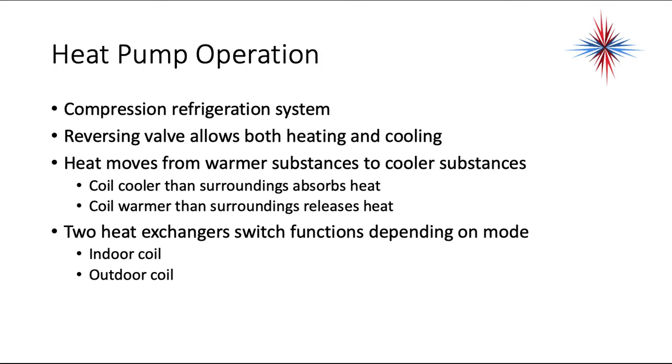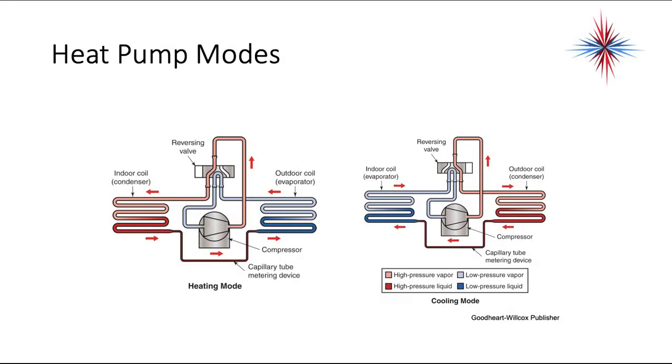Okay, two very important concepts. I don't care where these coils are, but a coil cooler than the surrounding air absorbs heat. A coil warmer than the surrounding air releases heat. There are two heat exchangers that switch function depending on the mode. So when we talk about heat pumps, we do not use the terms condenser and evaporator. We use the terms indoor coil and outdoor coil. They switch functions depending on the mode.